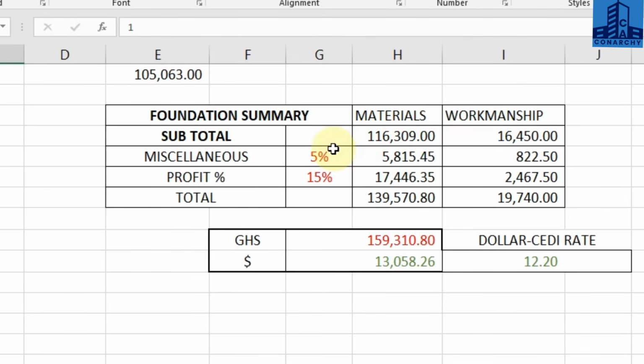So with everything, we try to find a miscellaneous. Miscellaneous is like a provisional amount of money that we place for certain things that arise during the construction. So these are just a miscellaneous amount, 5%. So the miscellaneous is usually 5 to 10%. So we decide to use the lowest, like 5% of this, 5% of that. That's a miscellaneous.